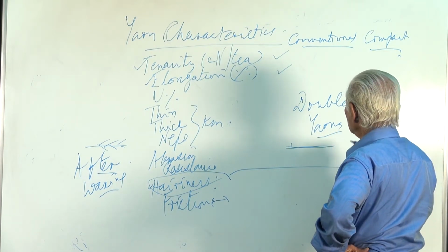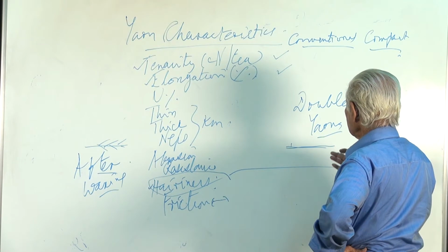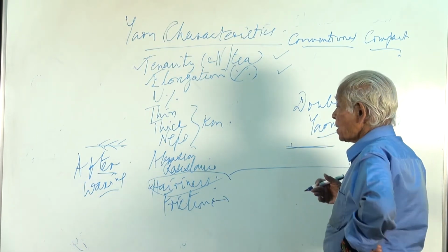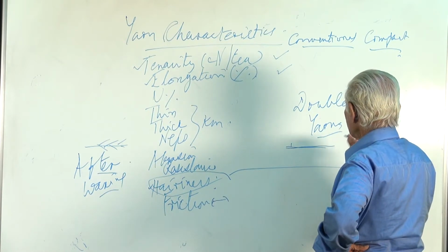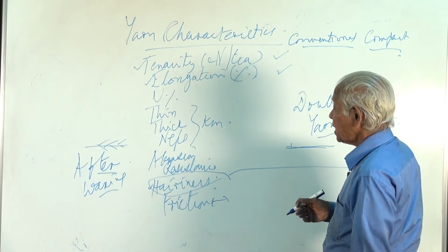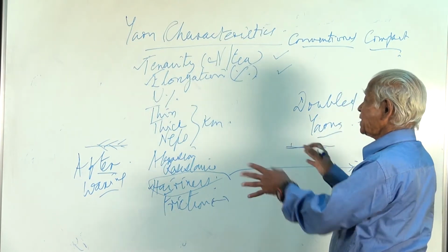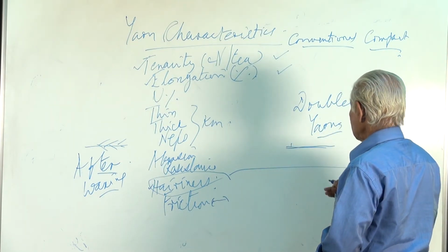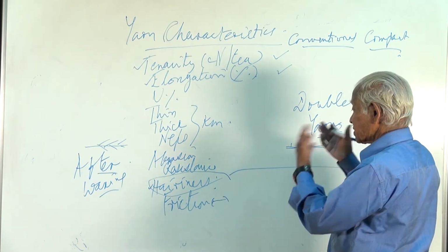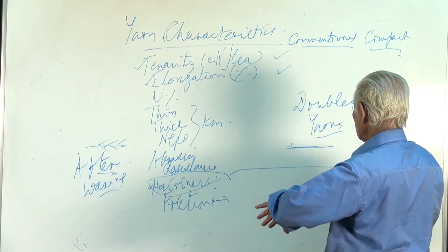And as I said, doubling is a value addition process. It improves the performance of the yarn. In fact, if doubled yarns are used for the production of fabrics, there is no need to give sizing also, and some mills avoided giving sizing treatment to these yarns, and it is an advantage also because when sizing is given, after some process, desizing has to be given to the fabric.